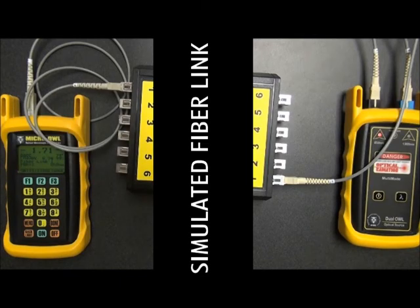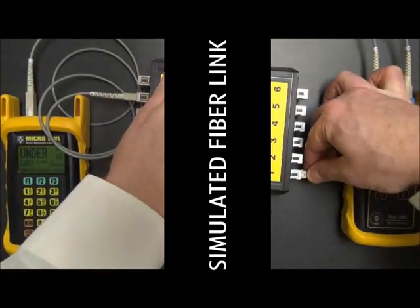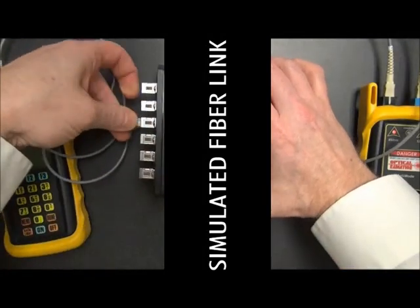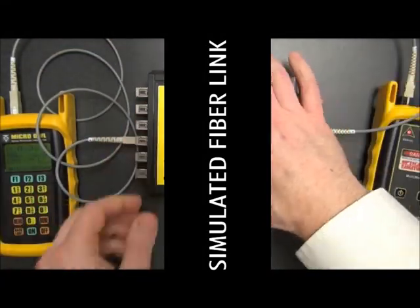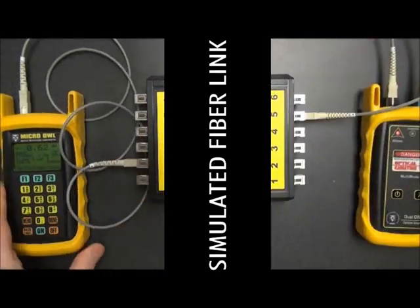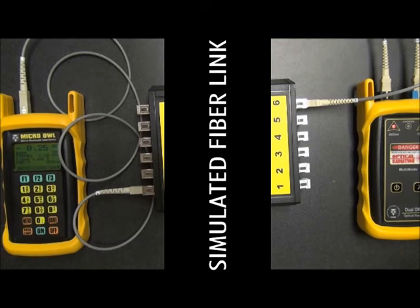So what I'm going to do here is demonstrate that. I'm going to speed up the process here, and I'm just going to store all 6 readings, and then I'll show you switching to 1300 shortly. Okay, so we've stored all of our readings at 850 nanometers for all 6 fibers.